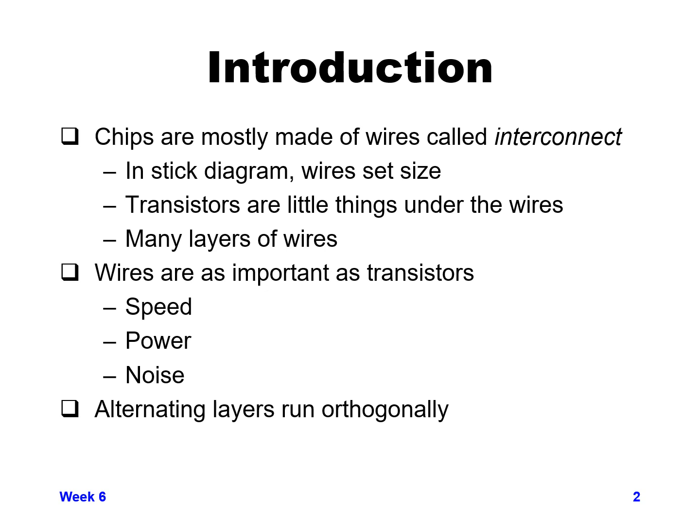So in reality, your interconnect is making up most of the process technology creating your IC chip. It is a lot of steps of interconnect, and your actual mask layers are a lot of steps of interconnect. So they're really a major part of your design. When you're looking at your stick diagram, the actual connections between your transistors and the wires of those connections a lot of times can determine the size that your cell is going to take up.